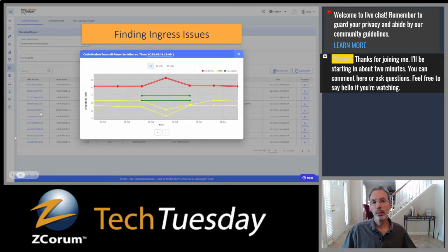It gives us a report of devices that are being correlated, this different kind of correlation between what's called the MTR or main tap ratio. That's a kind of pre-EQ analysis that we do of those digital taps, and then the cable modem transmit power. So we are looking at when the cable modem transmit power changes in relation to those digital taps. What that's telling us is that at particular times this modem seems to be fine and flat. There's no change in those two things, but then there are times when the modem has to adjust its pre-EQ taps.